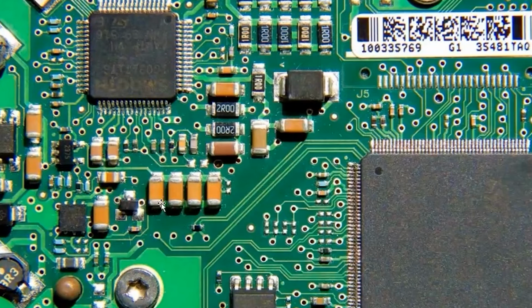This isn't the one that we've been looking at, the schematic or the PCB, and you can tell this is quite a bit more complicated, but you can see the same thing. This would be a microchip here, perhaps a microcontroller. You can see the signal traces, just like what we looked at on the PCB. All of these are capacitors, and then these are the vias that you can see. The signal trace comes down in vias and goes down to a different layer.